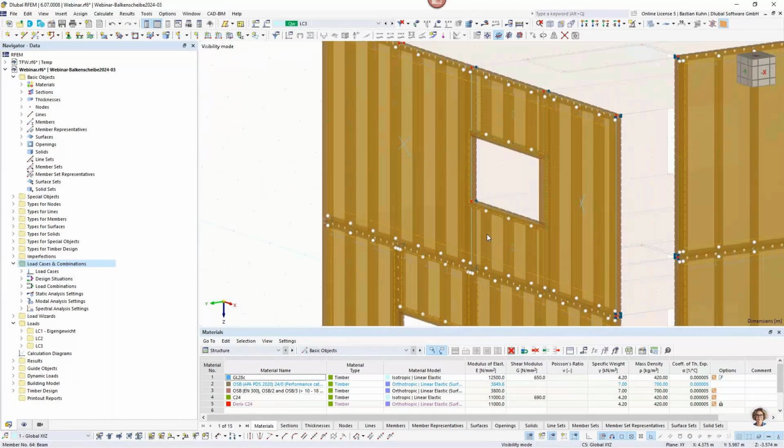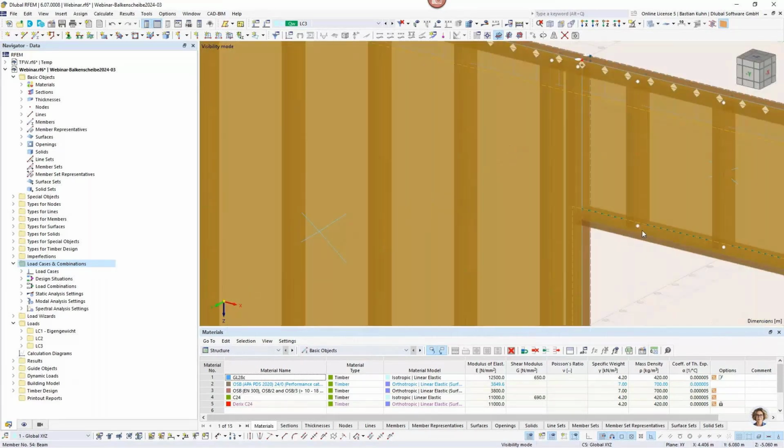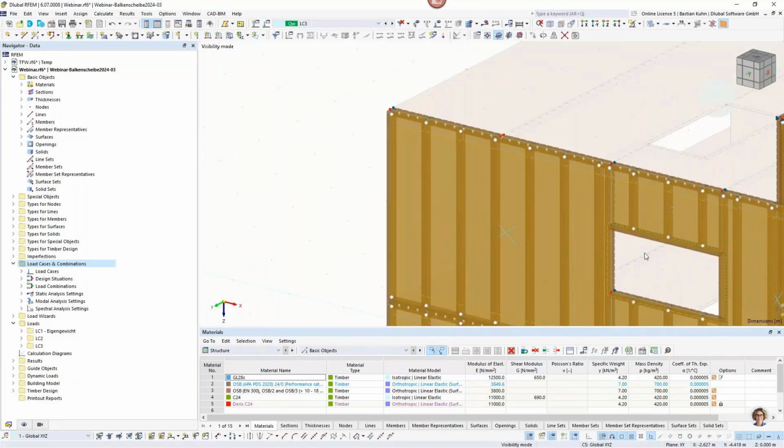What we do here in Europe is that we are using the top beam, or how you call it, on this window, and move it to the next stud. That's one of the possible constructions, and then it's a complete shear stiff, and of course it's nailed on every part wherever our OSB plates are connected or coming together, and there's always a beam or a post behind it. That's where it can be nailed on.